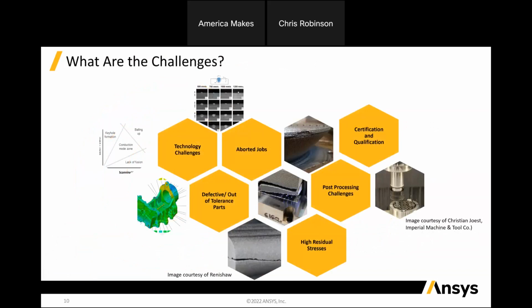So as we look at that, just another quick look into some of those challenges you have with additive manufacturing. Yes, those promises are amazing, but sometimes the challenges end up holding us back. Some of those challenges that can be addressed through simulation are your process parameters, particularly with the laser powder bed fusion process. You've got power and speed. If you get outside of what's called the conduction zone, then you can end up with porosity from overmelting, porosity from undermelting. You can get too much surface tension in the melt pool and cause balling, and other things like that can happen.